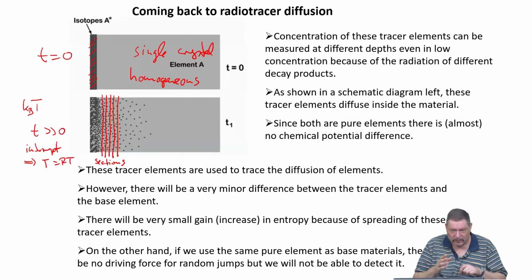So it means that if the diffusion process is very slow, or if you have only a very small number of diffusion channels in your material, still the radio tracer method can give you a result. For example, we are able to measure grain boundary diffusion in a bicrystal. Means you have a huge crystal, two bound together, and there's only one interface.